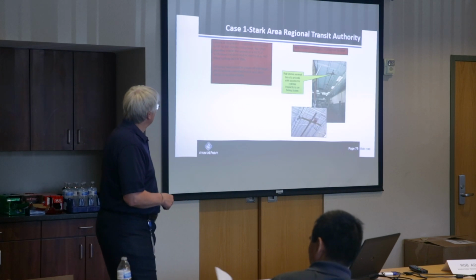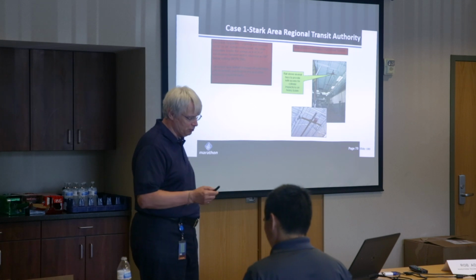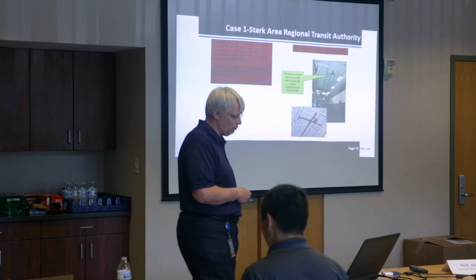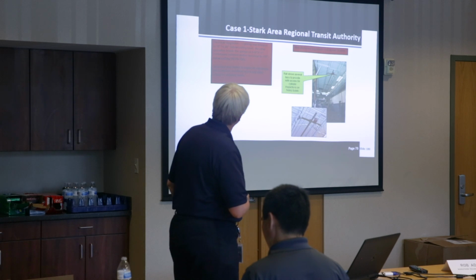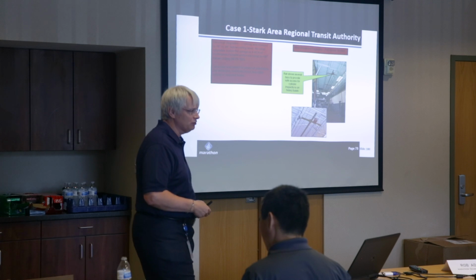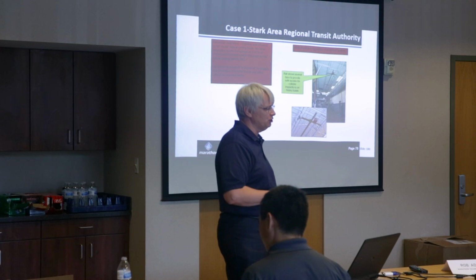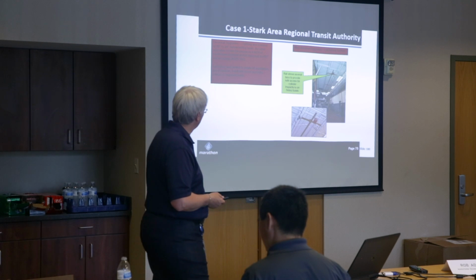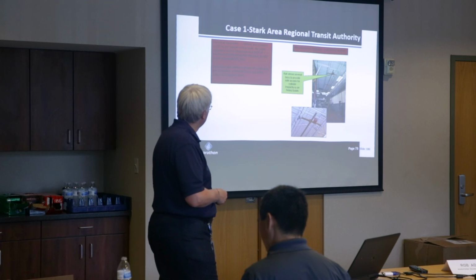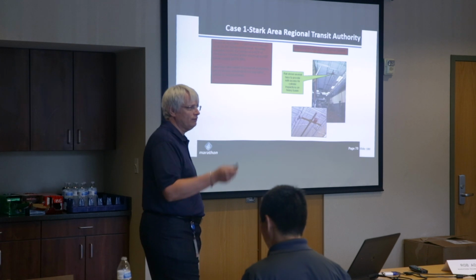In terms of electrical upgrades, they did lower the lighting. That's hard to see out there, but you can see it in your book. They lowered the lighting from 18 inches to 24 inches below the ceiling level, just to get it out of that zone. Although technically they didn't need to do that because they had the 4 air changes per hour. So they were adding some additional safety there.